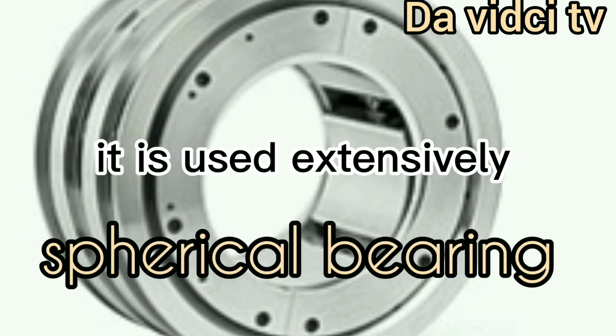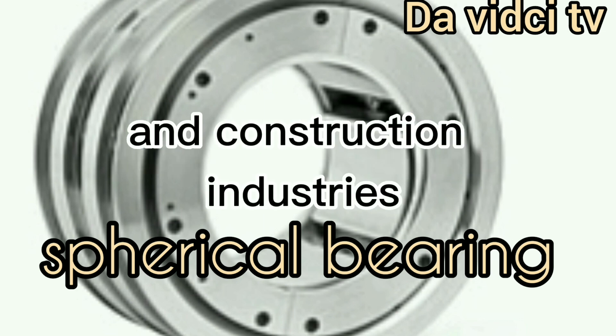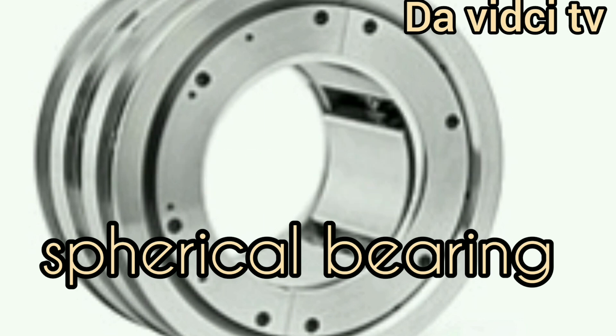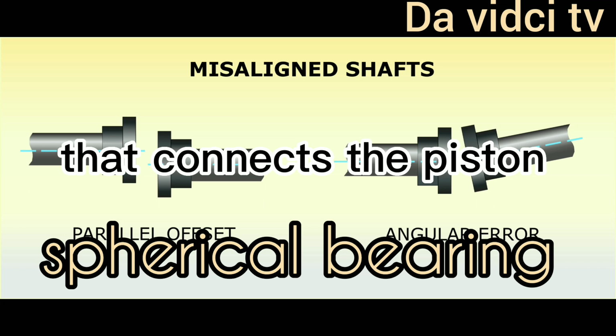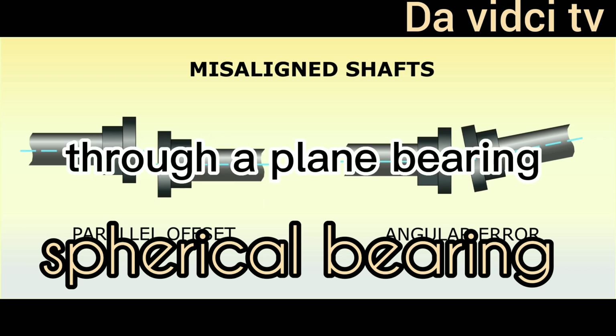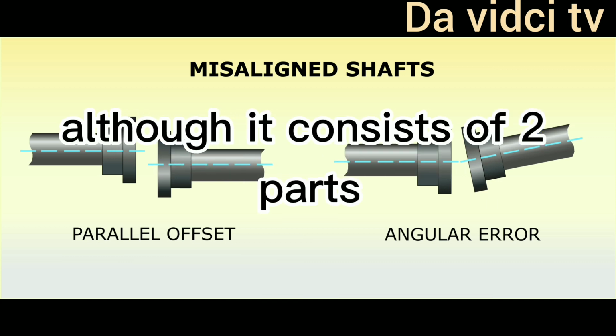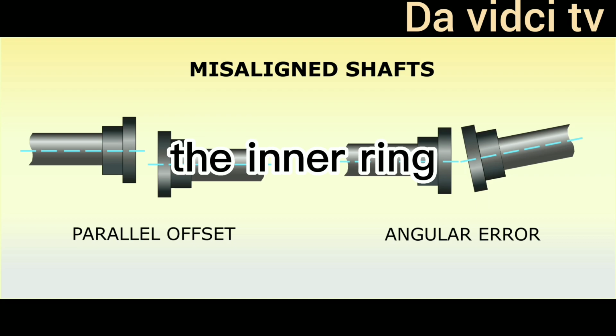It is used extensively in applications in the agriculture, automotive, marine, and construction industries. The gudgeon pin that connects the piston to the connecting rod in diesel engines is connected through a plain bearing. The spherical bearing is also a plain bearing, although it consists of 2 parts, the inner ring and the outer ring.